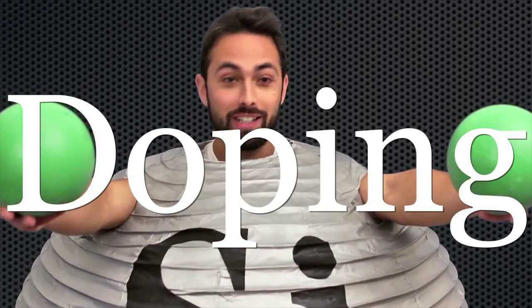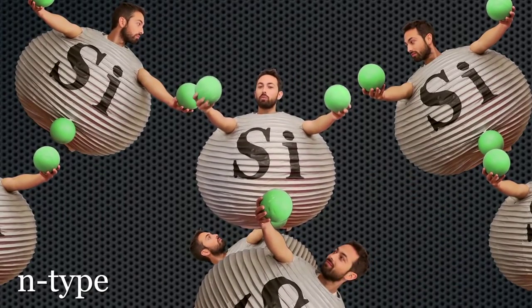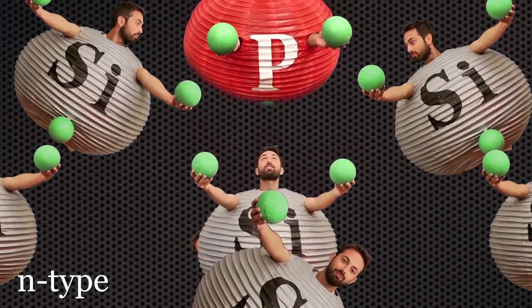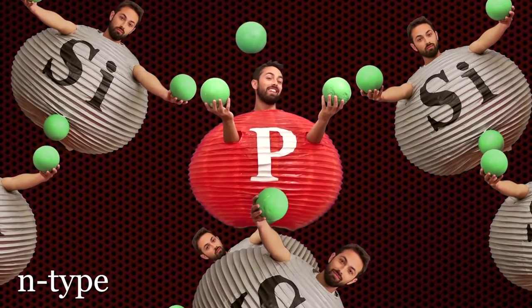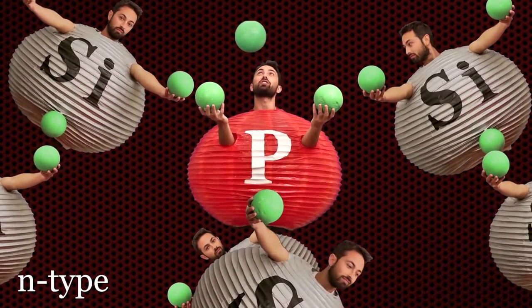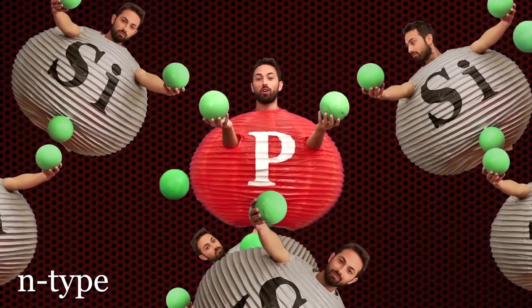Now this wouldn't be all that useful without a semiconductor's secret weapon, doping. You've probably heard of doping. It's when you inject a foreign substance in order to improve performance. It's actually just like that, except on the atomic level. There are 2 types of doping, called N-type and P-type. To make N-type semiconductor, you take pure silicon and inject a small amount of an element with 5 valence electrons, like phosphorus. This is useful because phosphorus is similar enough to silicon that it can fit into the lattice, but it brings with it an extra electron. So now the semiconductor has more mobile charges, and so it conducts current better.